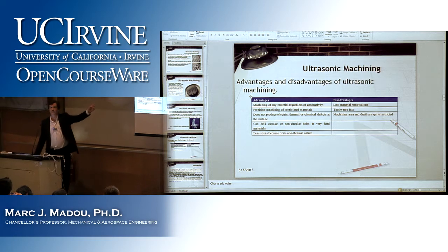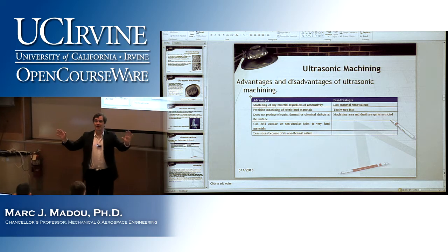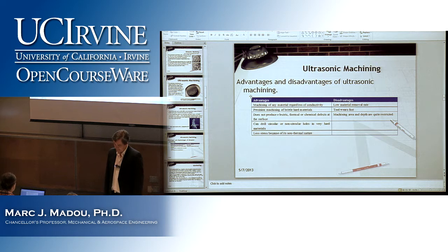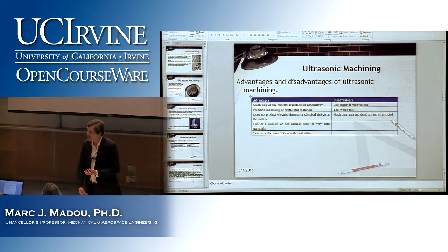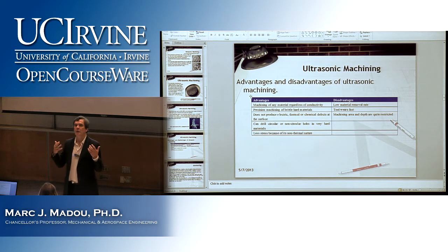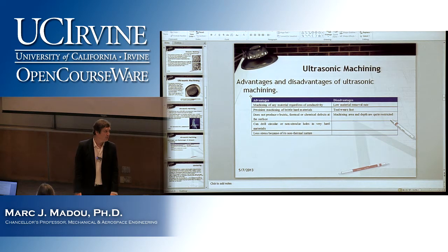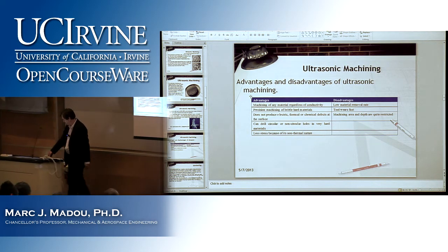And here you have a homework question too, right? The homework question here, and please don't answer and don't bring it up, right? Don't say, oh, I know. So we want to know, why does your tool here not etch or machine faster than your workpiece? And we have that question both for ultrasonic machining and for EDM. So in a way, we want to know why is there asymmetry in the machining? Why doesn't your tool, in both cases, machine, corrode as fast as your workpiece, right? So that I will not ask in the midterm.